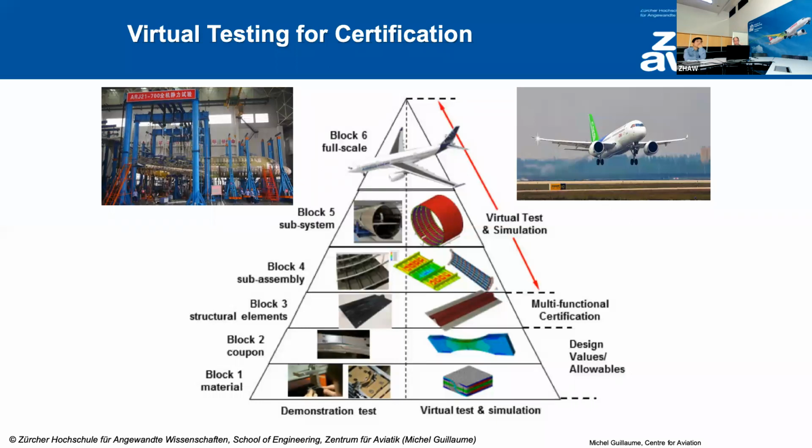But I think we are good today. All our tools and methods are calibrated for wing tube design aircraft. So for that, we are good. If we're going to blended wing body design, I think we should go more back to basics, to the physics, and adjust our tools and methodologies. So we need to do more testing in wind tunnel or structure tests to get familiar with the new concepts. And then we can calibrate a simulation basis and then go into more simulation and virtual testing. So if we really come up with new designs, which don't have experience, then we need to maybe go a step back and do more tests and validate all the methods and technologies.